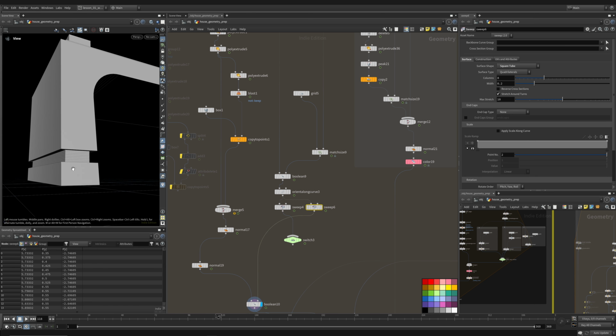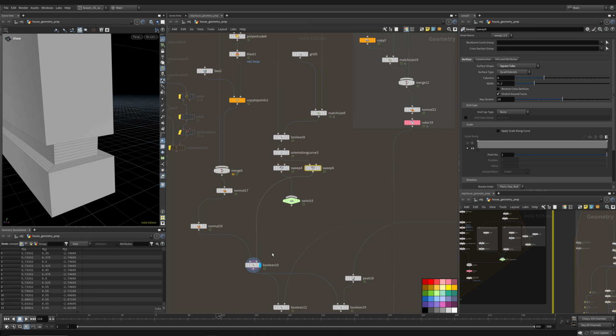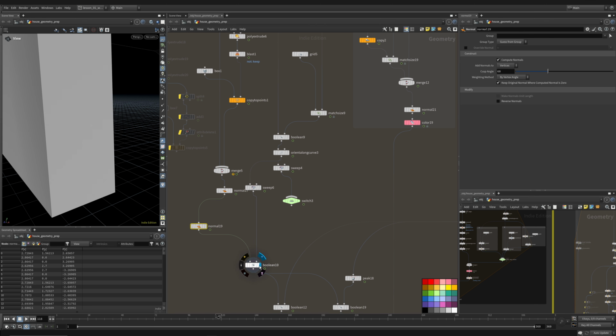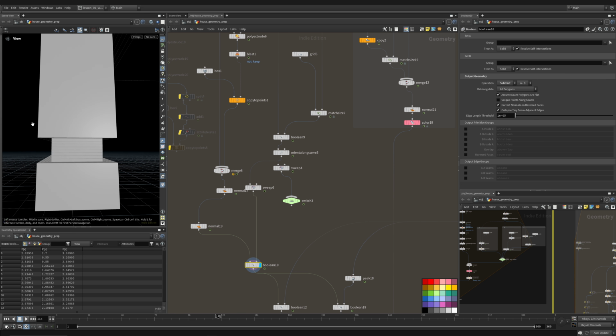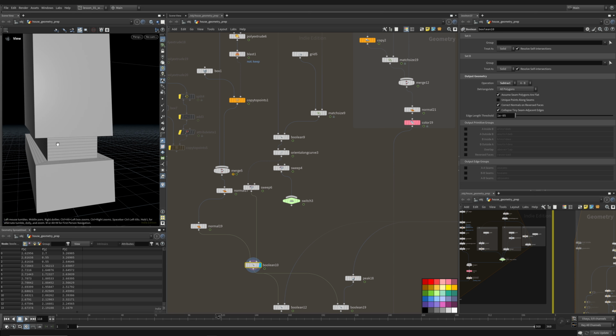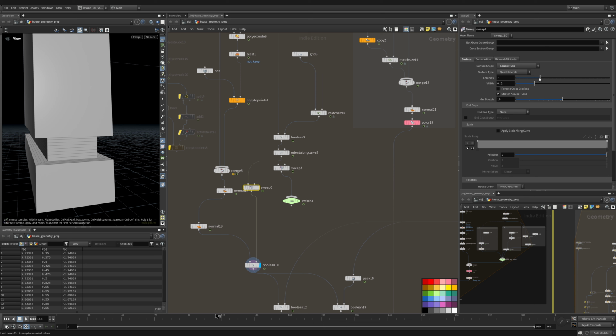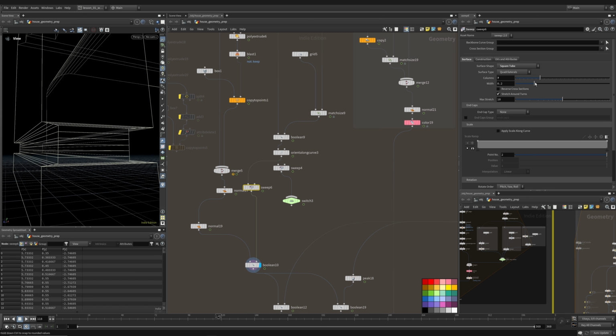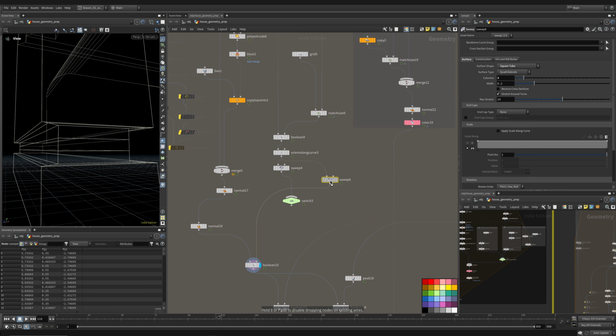And we'll actually notice for the Boolean, the resolution inside the cutting area is defined by the resolution of the cutting surface. So this has a lot of resolution. So when I cut, it will add that resolution to this new object. But if I don't want these lines, I could change the resolution on my sweep. Now you see they go away because I have changed the resolution of my cutting object. So that's one way.